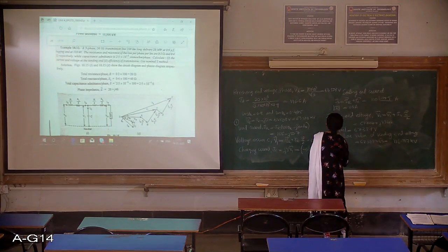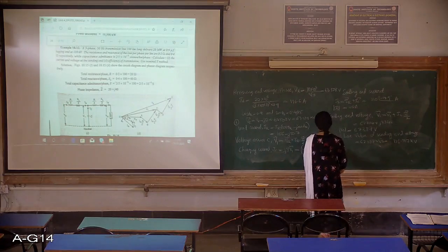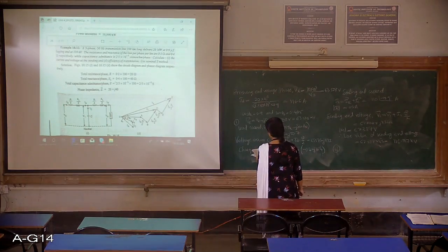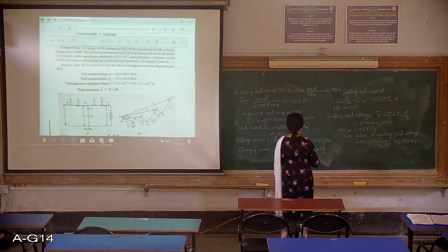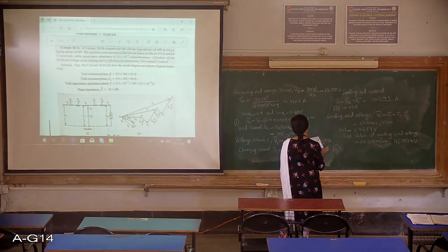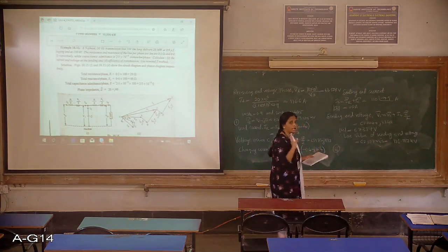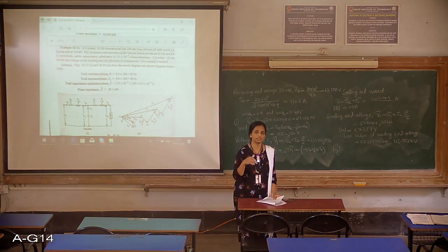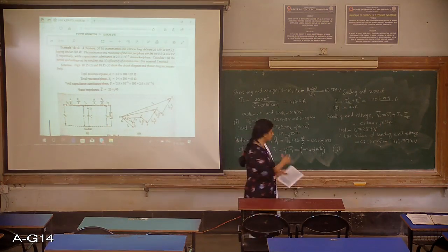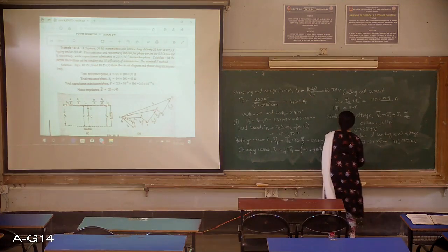And finally, the third one they have asked is transmission efficiency. Yes. So now you know the power. So how much they have given? Power 20 megawatt. Okay. So how do we define the transmission efficiency? Output by input. So they have given the output as 20. Now what will be the input? Input will be output plus losses. Clear? So now we don't know the losses. So transmission efficiency is 20 divided by 20 plus those losses. So losses are nothing but your I square R loss.